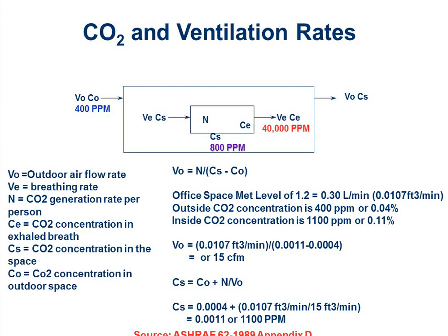So it's not that ASHRAE just randomly made up all of these numbers and said, oh, you got to bring in, whatever, 10 CFM per person in a school and 12 CFM per person in a daycare and 5 CFM per person here and there. Those numbers were not made up. They were backwards calculated from the stabilization rate of CO2 generated per person versus what I have in the outdoors. So all this math, and you have it on here as a kind of a reference.